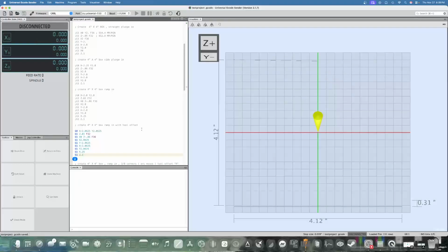And I did the same ramp that we did previously, just with corrected dimensions. Instead of 2 inch, now it's a 1/16 wider. Instead of 2 inches, it's a 1/16 taller. And then overall same process that the last example was. Feeds over, feeds down to my wanted start point, 10 thousandths above, feed rate of 32 inches a minute. It's feeding again. It's going to X0, Z minus 60.